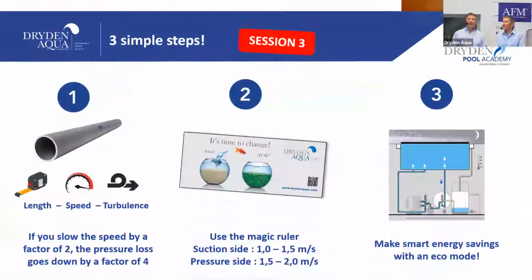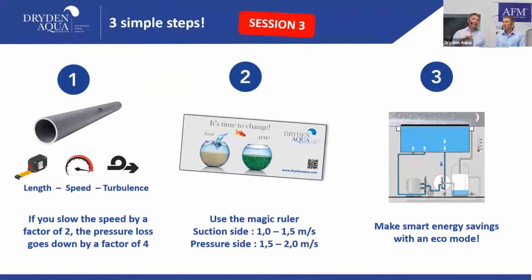Okay. Last point, that's also for indoor pools. And I can explain this. If you run it 12 hours in the normal mode, when you swim, for instance, in a jacuzzi or any indoor pool, and then you go in the eco mode during nighttime for 12 hours, then your dehumidifier will stop after a certain period of time. It will not run all night long, maybe only 2 hours instead of 12 hours. And this is where you see the energy saving.